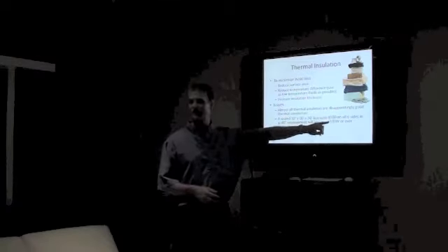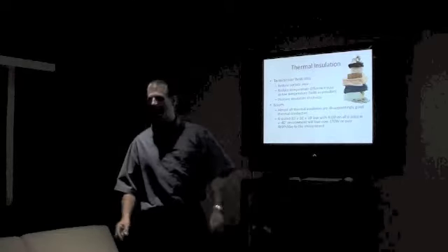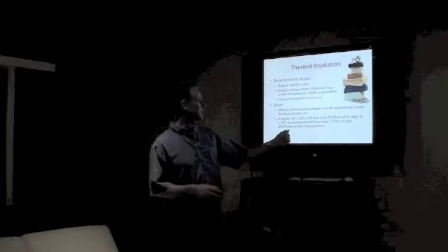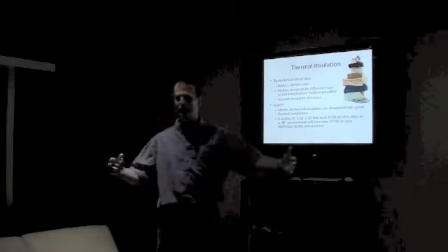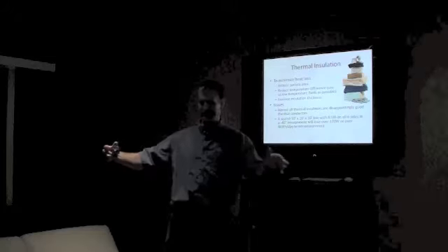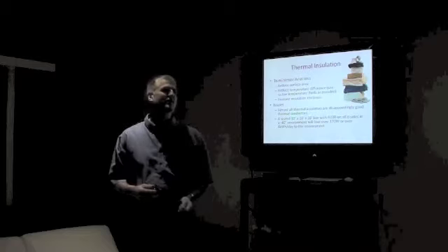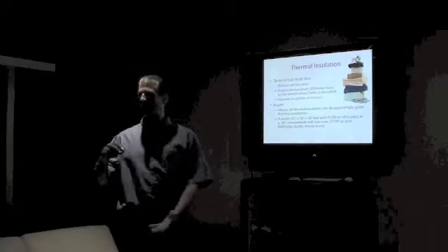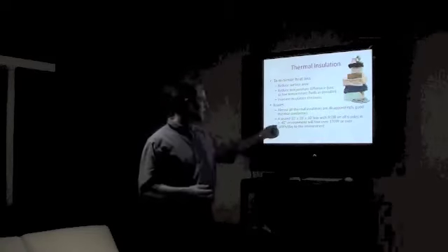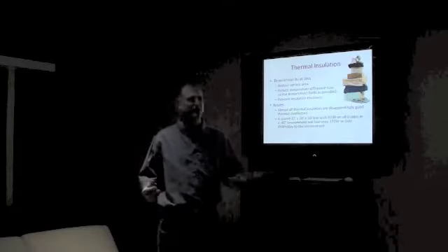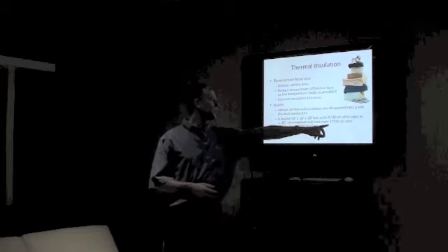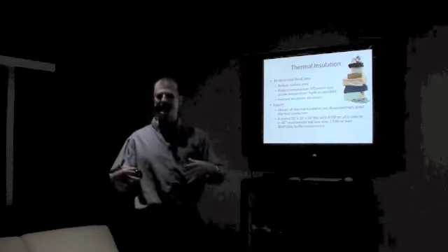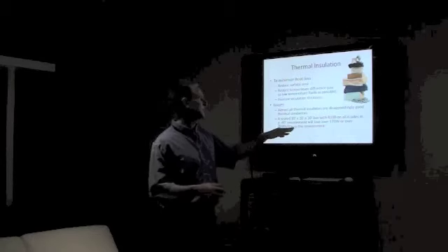For example, if you consider R100 walls very well insulated walls, I did some calculations, I hope I got it right: if I had a 10 by 10 by 10 cube, which isn't much bigger than the area we're in here, maybe a little bit taller, and you insulated all 6 sides, 4 sides, the top and bottom, with R100 insulation, and it was a minus 40 degree day and 20 degrees Celsius inside the box, it requires 170 watts to keep that box at its temperature.